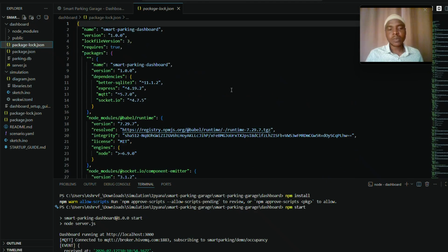So up to now, the project is able to detect the available spaces for parking, able to detect whether the parking is open or full, it's able to detect how many spaces are occupied and how many are empty, and also it is connected to MQTT, which is the end-to-end protocol or set of rules enabled for devices to communicate, and it is also connected to a database so as to store all the real-time information and the past information.